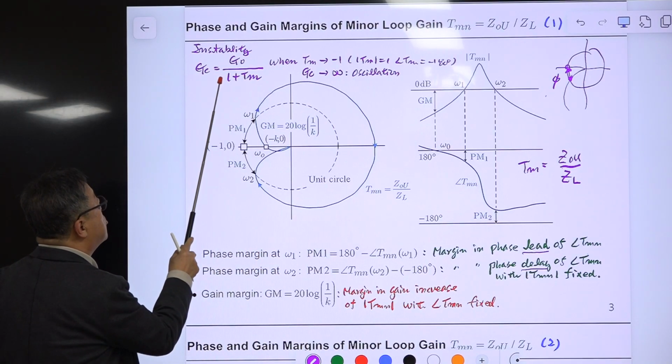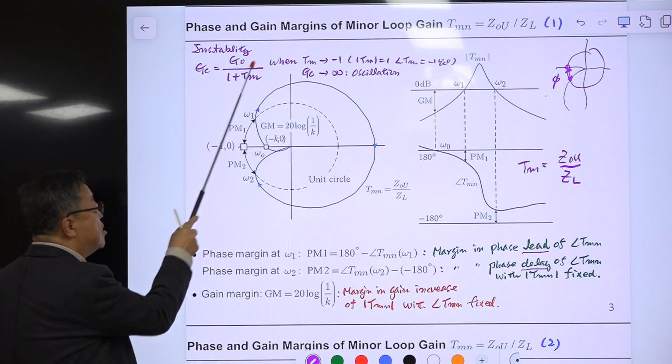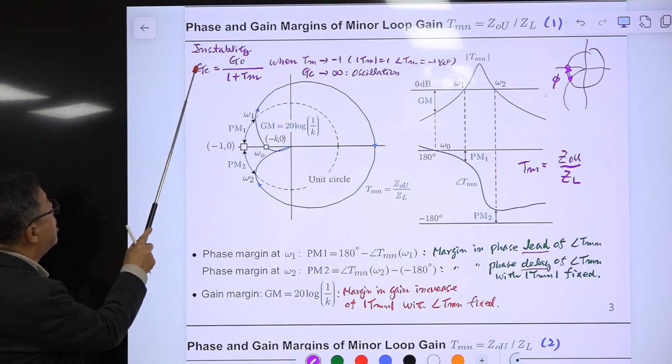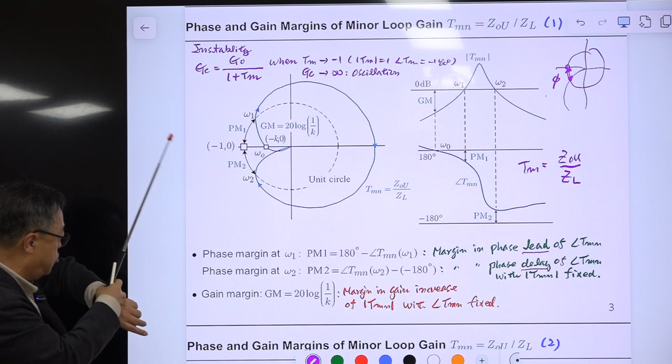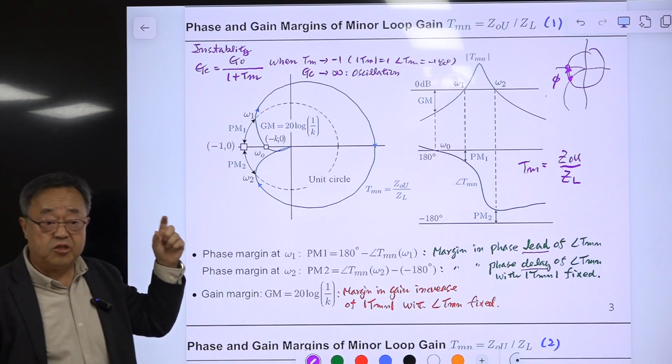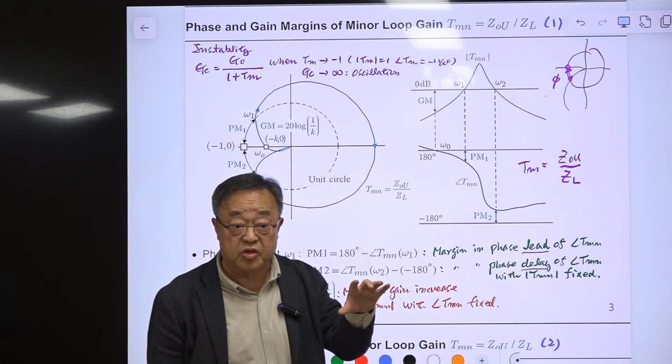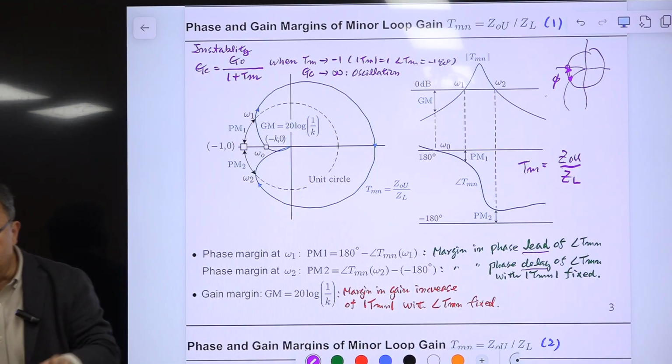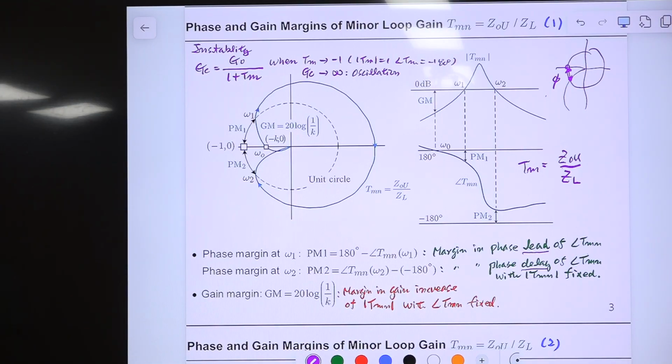So this is the closed loop transfer function, and this is the open loop transfer function. The relationship between the closed loop transfer function and the open loop transfer function is this one. This is the single loop system, and the feedback is extracted at the output of the transfer function. There is a special case. In your control book, they are considering all this special case. In electronics, people are using this formula illegally for all feedback amplifiers. That's their fault, that is wrong.